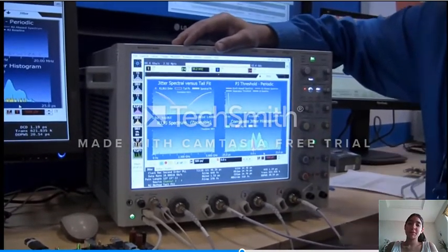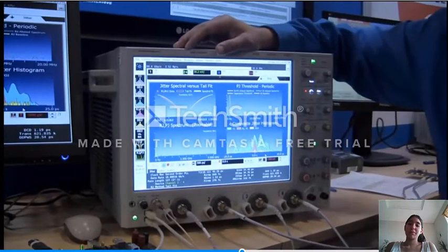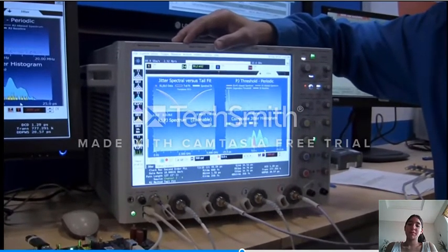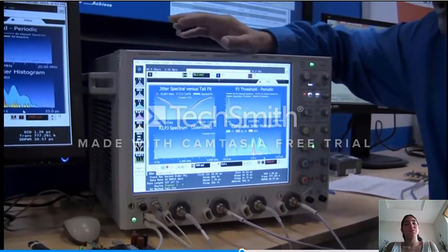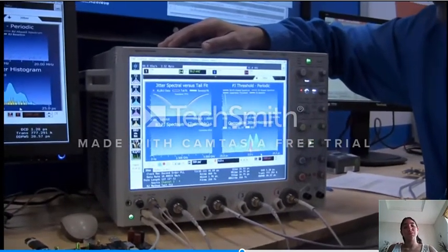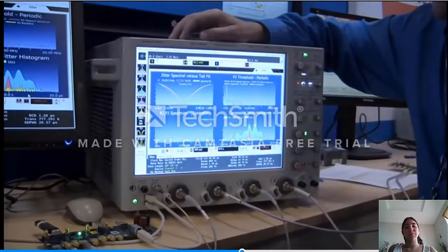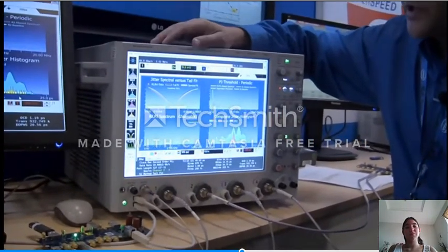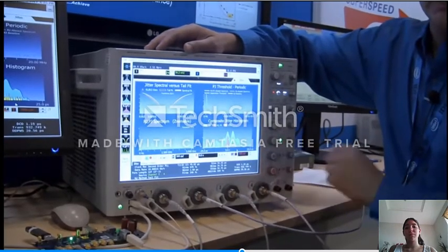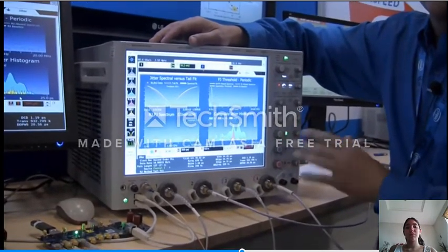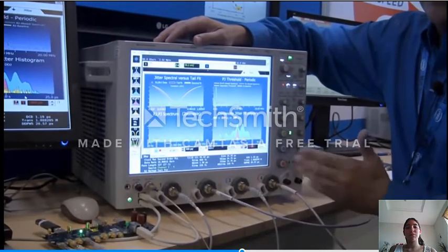So if I understand correctly, you're ready to go to test a 10 gigabit per second USB 3.1 transceiver. We are ready to go. We have the baseline equipment requirements nailed with the scope bandwidth requirements and the bit error rate tester. The underlying algorithms will need to be fine-tuned and tested against the test spec requirements that are under development today, as well as validated against real silicon.